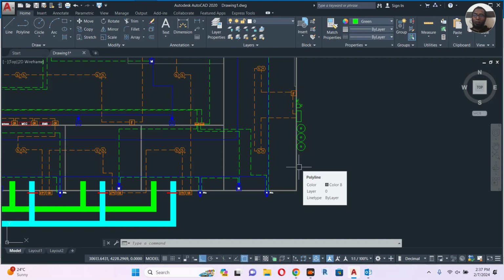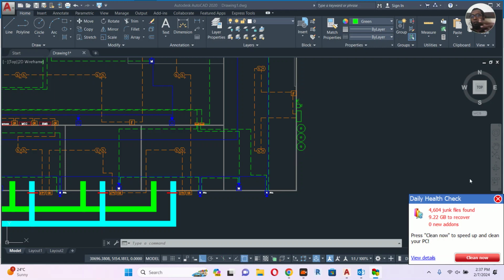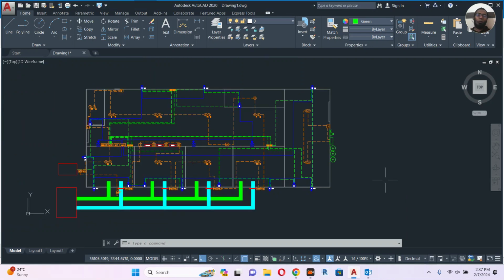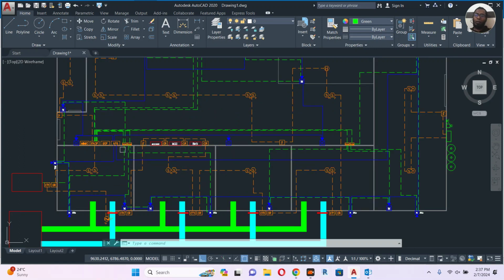The stage, the triggering stage. There are too many stages, like 4, 5 stages. You have to check with the specialist how many monitor modules they need. So whatever they want to monitor, we need to provide one monitor module, and we can make the programming through the fire alarm specialist to the FACP.